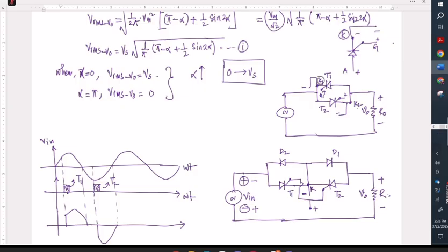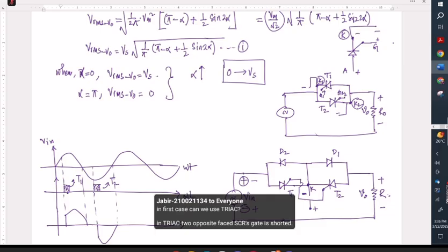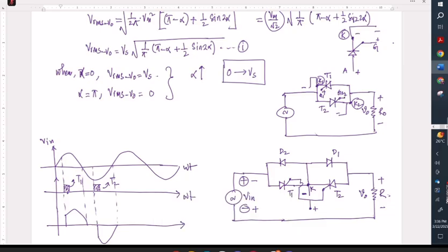But is this cathode the same as the other one? No, sir. So in that case, you need another circuit that will provide a positive pulse to G2 with respect to K2, because they don't have the common cathode terminal. You got my point, right? Yes, sir. So how can we avoid that? We can avoid that by modifying this circuit to another circuit incorporating two thyristors and two diodes.